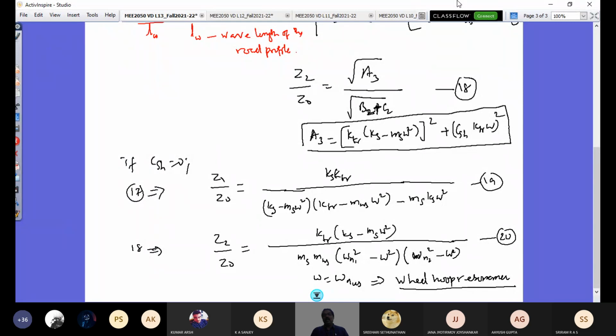So when you go on a vehicle on the road surface, the road irregularities can excite your tire wheel assembly, which will be bouncing. But you see, the vehicle body would be having less, and that is all because the energy is mostly taken away by your unsprung mass. So the lesser the amplitude getting to your vehicle, the better the ride comfort. That is the default design in a passenger car.